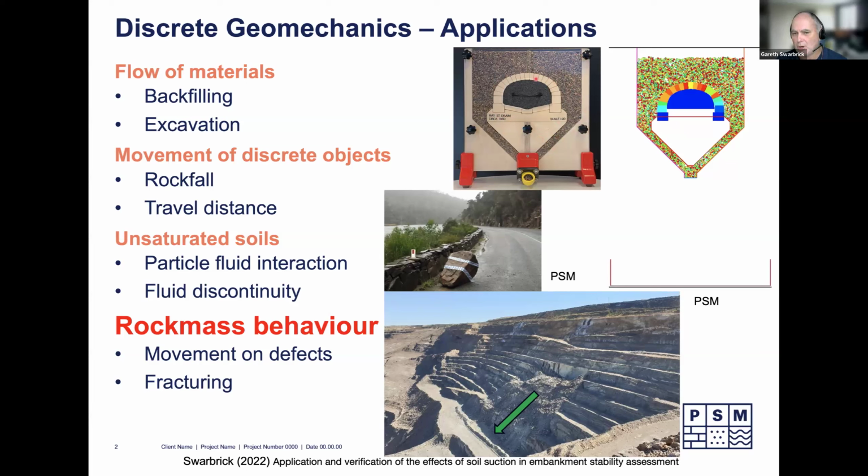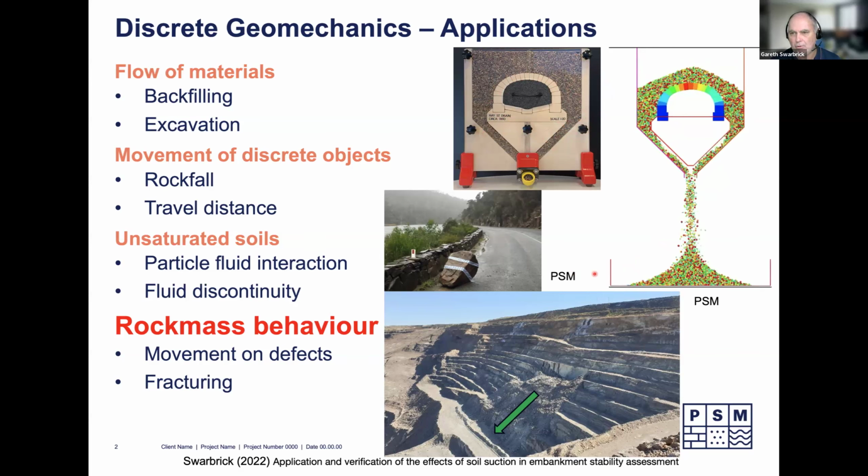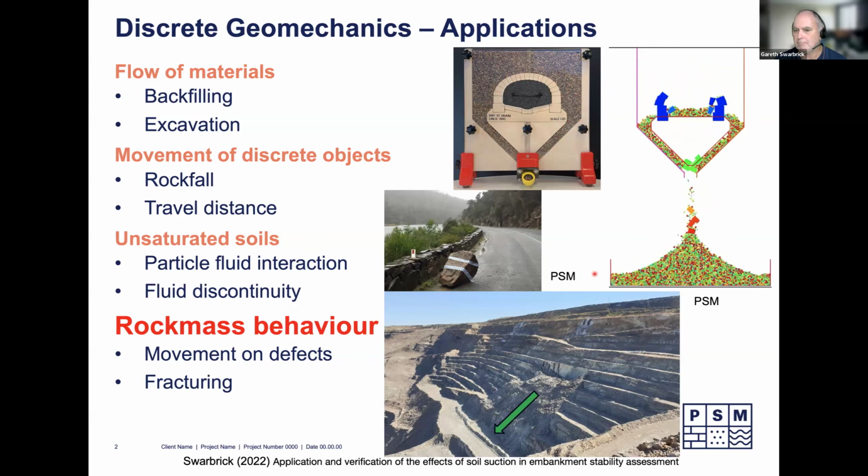Interestingly, this became an internal competition inside the company. We all had to guess and see how well or how badly our predictions would do. One of the best simulations actually used particle flow code to show what that behavior might be and how that arch might perform if that material was removed, and how that support would no longer be isotropically controlling that archway.